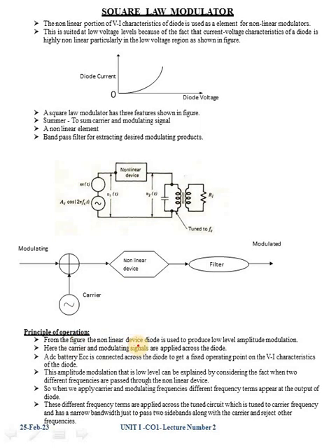Now the principle of operation. This is the circuit diagram and this is the block diagram. Here we are applying our carrier signal and input signal. Modulation takes place in the non-linear device, which may be a diode or a transistor. Whenever the device gets a positive voltage greater than the threshold level, the system automatically starts conducting. So this is the basic principle.